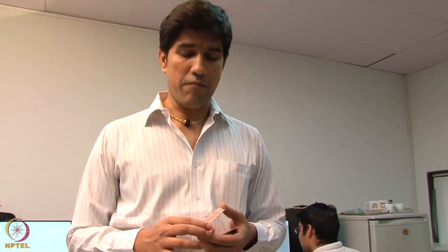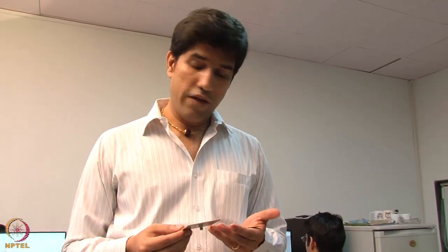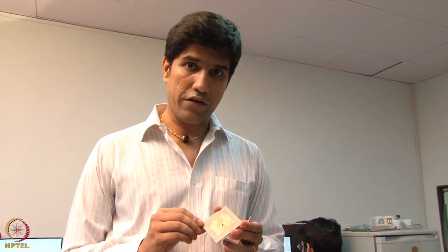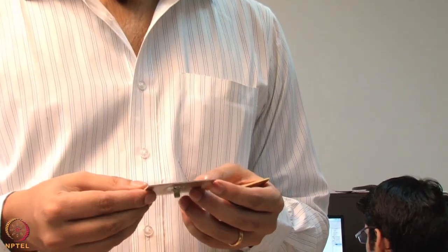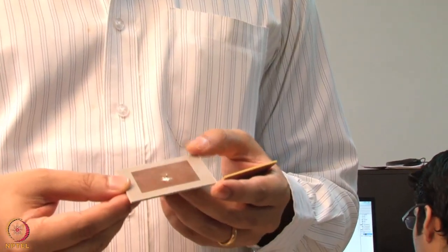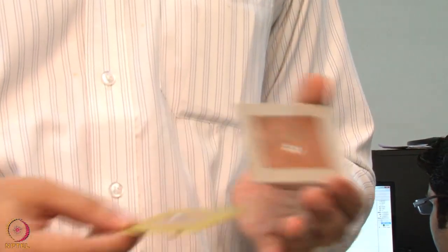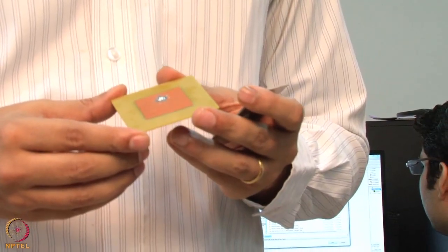We are in the antennas lab, which is one of the most important labs in microwave engineering, where we simulate various kinds of antennas. Today we are going to look into a special type of antenna, which we call a patch antenna. We call it a patch antenna because we have a metal layer sitting on a dielectric. In this case, we are using an FR4 substrate, which is fire retardant, with a dielectric permittivity of roughly 4. We also have another material, Arlon, with a relative permittivity of 2.55.